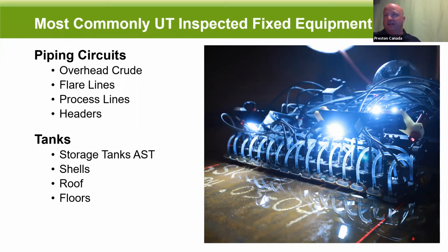We filter the data because we're taking millions and millions of readings a shift. So we filter the data and present it in a way that we're not trying to flood you with too much data, but we can retain those A-scan signals for every inspection. And your subject matter experts, your level 3s, could dive into the data, cross-reference what we have, and do their audits. So we retain all of that. You get the best of both worlds.